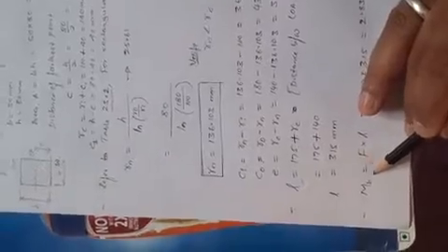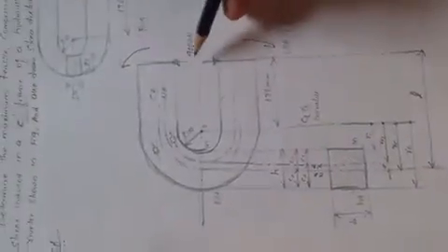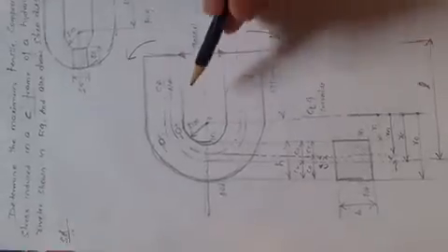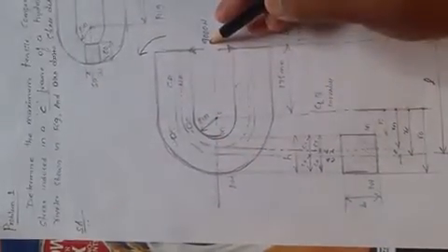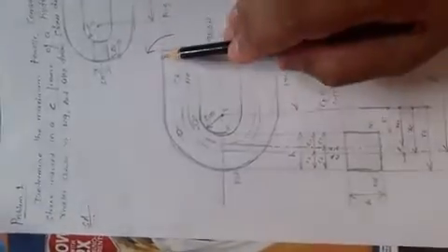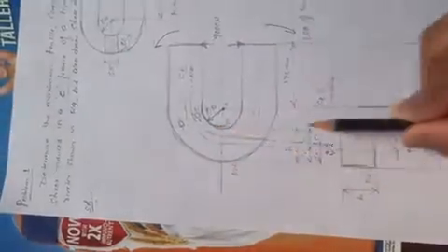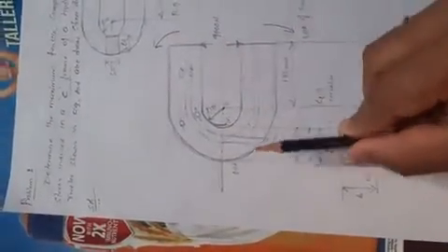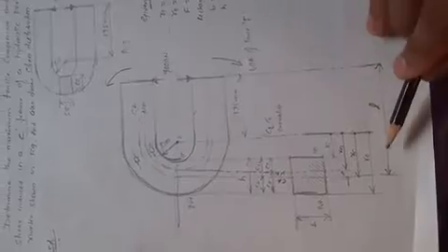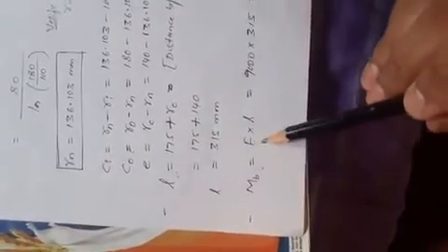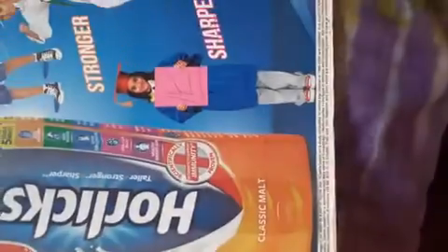Then after that, one more data is the bending moment. Due to the force applied here, an eccentric load occurs on that section, which directly transfers the load to the cross section, tensile in nature. And force into distance produces what? Moment. Then what is the external moment here? Due to the force, the moment occurred is force into L. This is the moment that occurs.